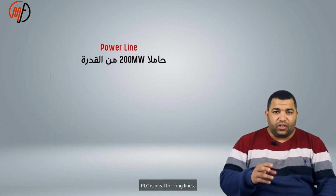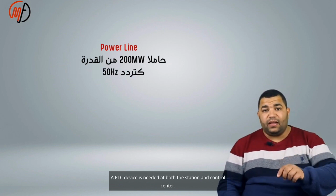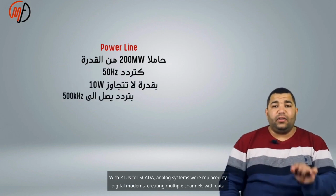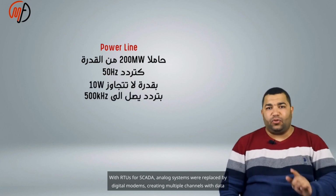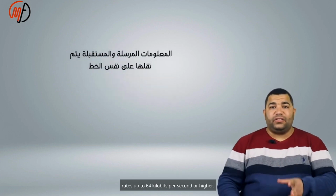PLC is ideal for long lines. A PLC device is needed at both the station and the control center. Initially, PLC networks supported direct telephone links. With RTUs for SCADA, analog systems were replaced by digital modems, creating multiple channels with data rates up to 64 kilobits per second or higher.